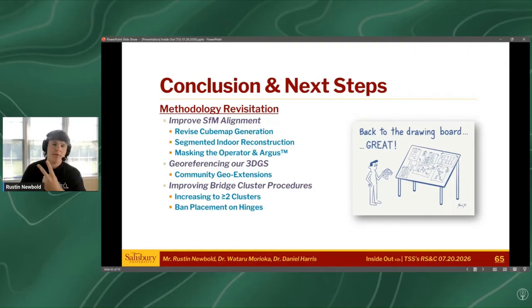The second thing of note for improving the project is georeferencing our Gaussian splat. This might sound a little bit confusing, but the splat that you just played around with on the outer portion of the model is actually not georeferenced in the form it currently is in. It's technically scaled properly. However, all of the georeferencing data still lies within RealityScan, which is why I perform my quality check in RealityScan. So finding a way to export that over is of importance. And there are some extensions with that.